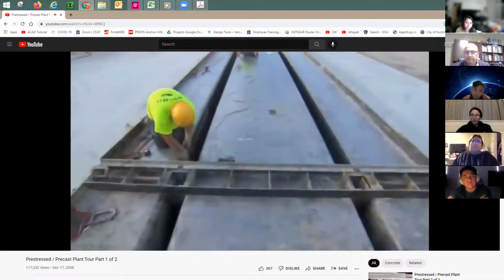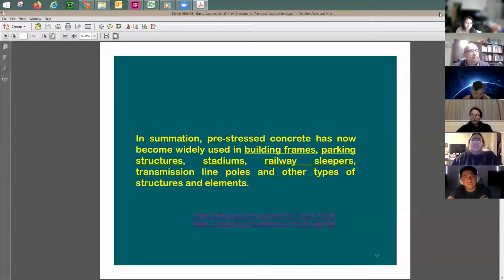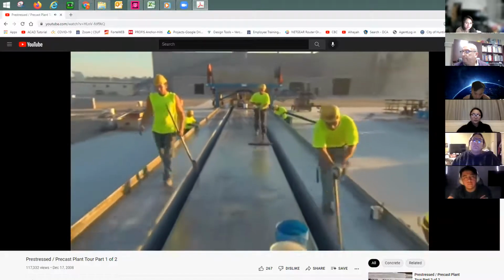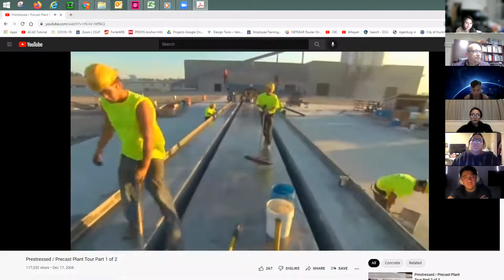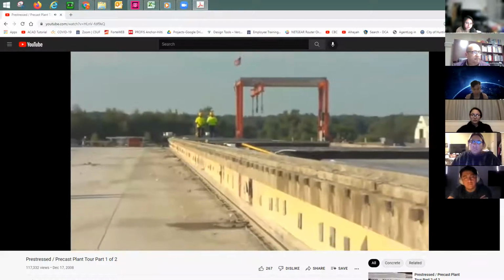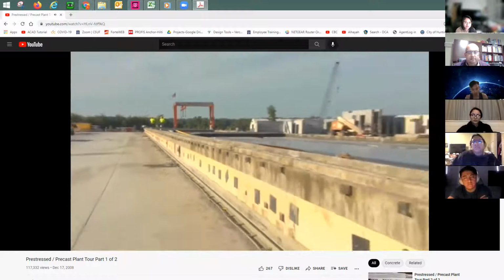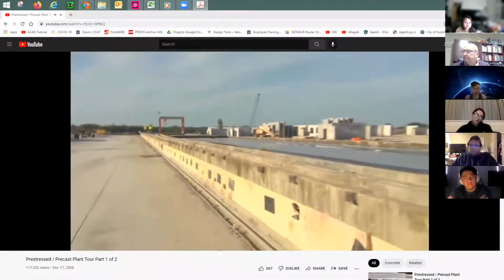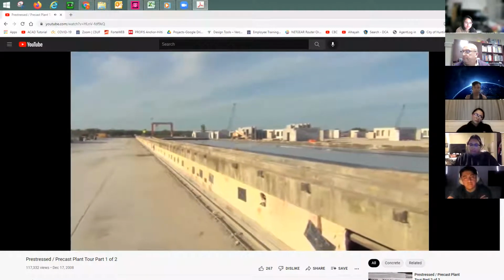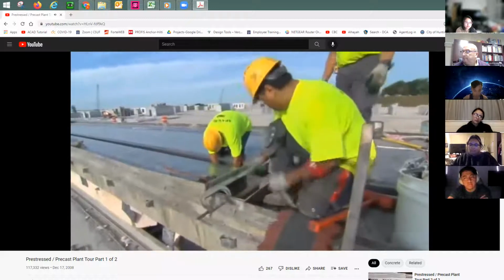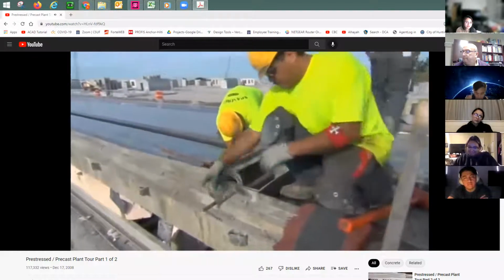The first part of the process is setting up of the form. A thorough cleaning of the entire form is done with basic labor and appropriate cleaning equipment. Setting the side forms, or in the case of a typical double T, the forms may be fixed forms with an appropriate draft to allow for easy stripping. Once the bed is clean, it's ready for setting up today's cast.